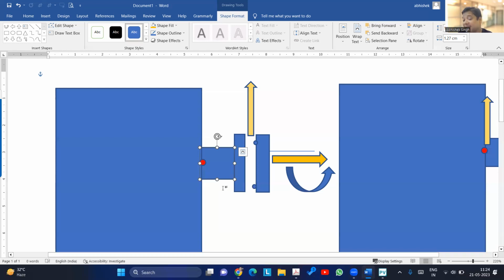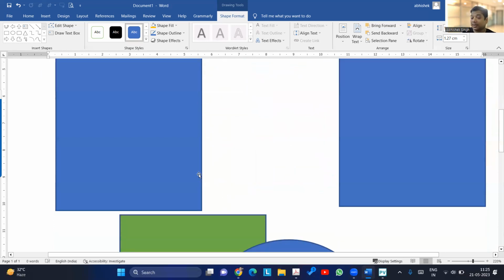For the nozzle, you have the tensile load because of pressure, so add that and check with allowable. The radial load P will create a compressive stress, so you need to calculate that and add it to the compressive stress because of moments. With the no-pressure case, you can check what the maximum is. That is how the nozzle necks are qualified.